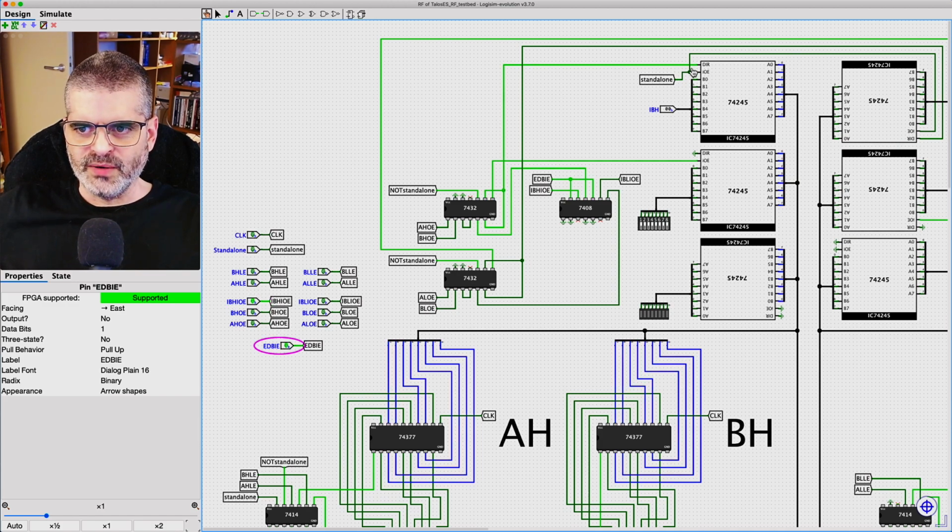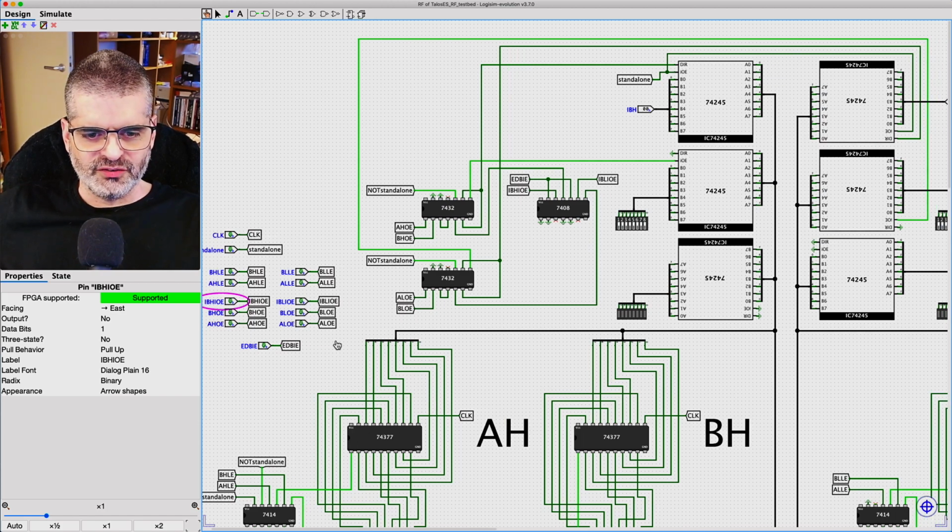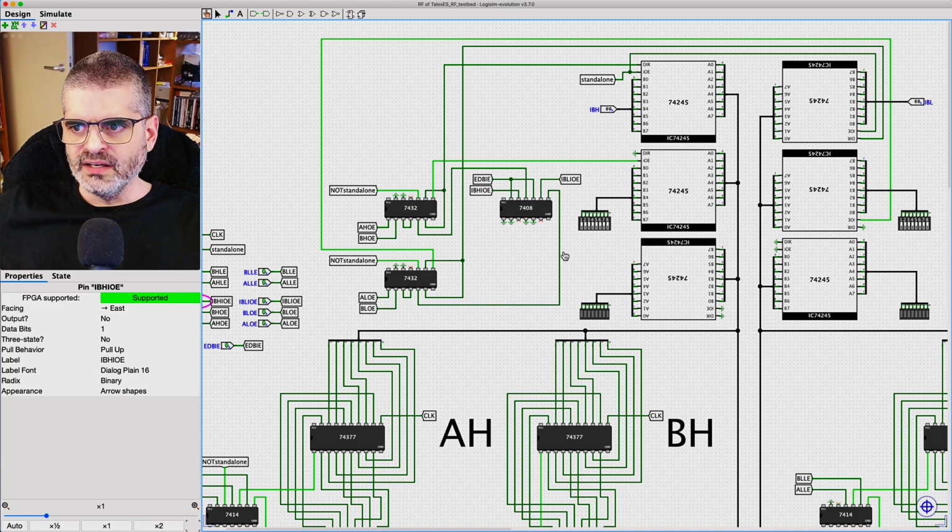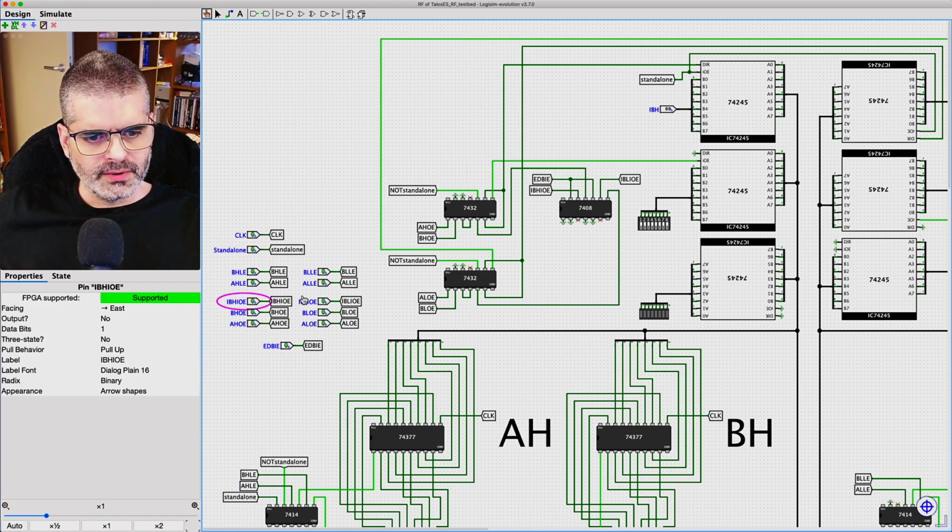And the direction bit would change, because now that value has to be taken from the local bus and driven out, as opposed to the value outside coming through the backplane connector, being read and then driven into the local bus. So it works for the high side. The same thing for the low side. It's no different. I will run it very quickly to show you.